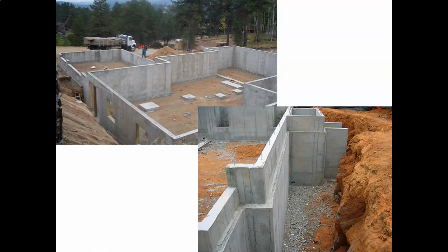Often, if we have an occupiable basement, and these two pictures are of an occupiable basement, it appears, and they are the foundation walls. And here are the anchor bolts at the top of them. This is a ledge for bricks, and then all this gets backfilled, of course. And then here we see some column footings. So we expect there to be probably steel columns supporting a beam, kind of jog here in some strange way, but somehow, some configuration, there's a beam up there.